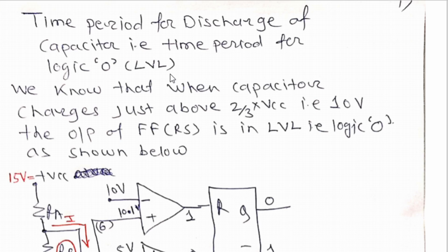All of you know that in the previous lecture we connected the circuit for IC555 as an astable multivibrator, and when we applied the power supply, we know that the externally connected capacitor C starts charging through RA and RB. The moment we connected the power supply, at time t equal to 0, we have considered that our capacitor was initially discharged. And because of that consideration, the output of the flip-flop Q becomes logic 1.